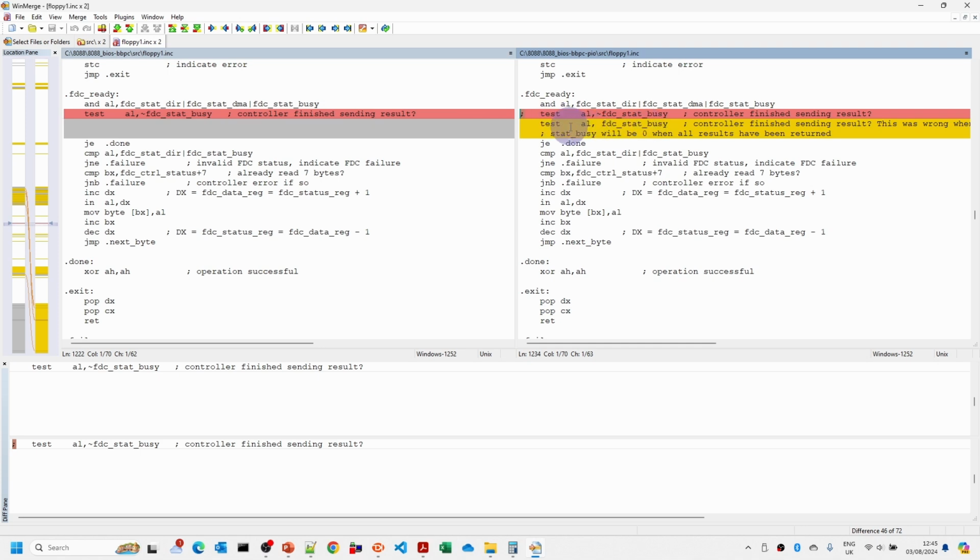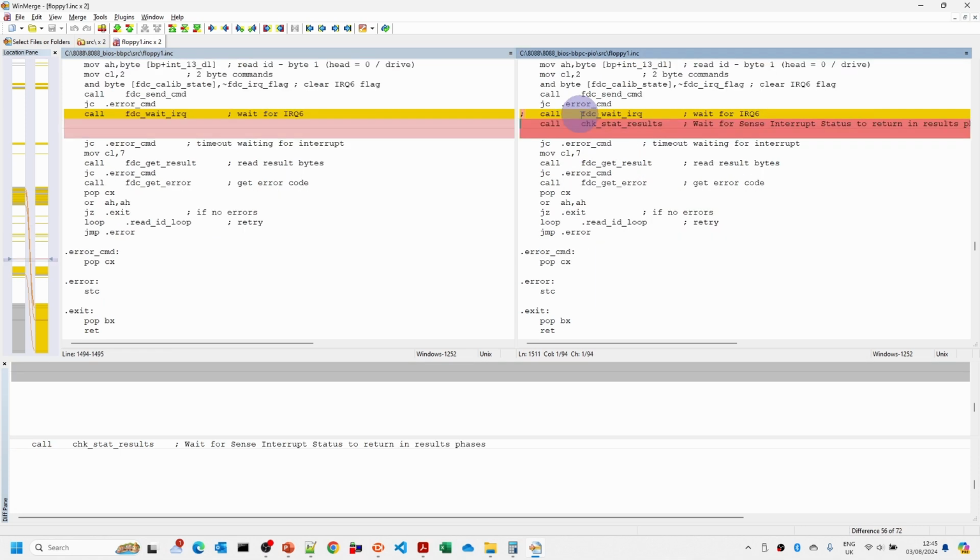But when using programmed I/O, this particular check here, which was masking out some of the status bits, was testing specifically with this value here, which basically says, apart from the FDC status busy bit, set all the others to 1, and this wasn't actually doing what I think it was supposed to do. So I've changed this, and this seemed to make the code work. So it's unlikely to be an issue if you're ever using DMA, but it was a problem for programmed I/O.